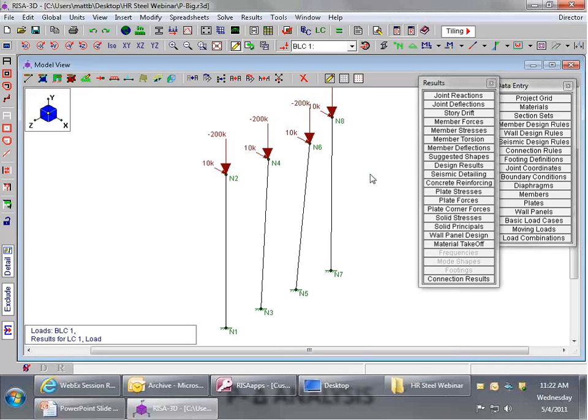It's the program telling you that in reality, when we run the iterative process, your structure is actually collapsing due to lack of stiffness. The most common thing that results in this is that you've sized all of your columns for gravity-only loads, and then you start applying lateral loads to the structure. And when you apply a lateral load to a relatively flimsy gravity-only column, things will tend to just tip over.